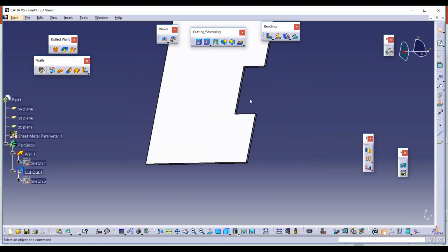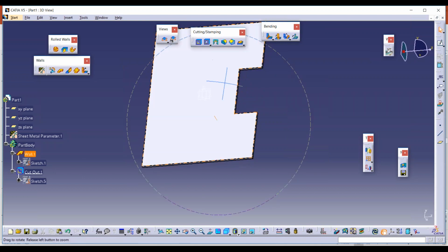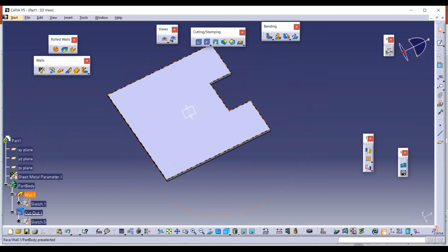So that kind of structure can be done only on the secondary parameter. If I have created another vertical plane here, there I can bend with a small line. So only the entire length will be considered for bend from flat. It will not consider half of the length. Even if you draw a half line section, it will be considered the whole entire length. Okay.